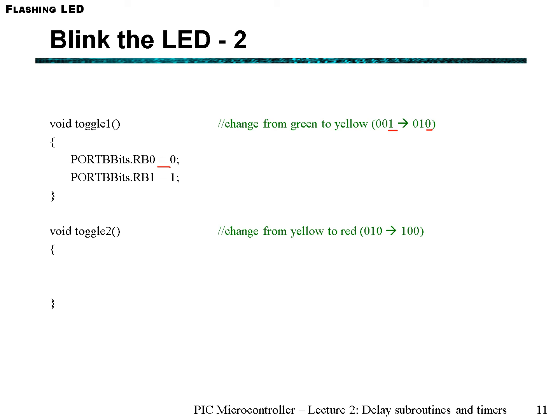So we're clearing bit 1, which is the yellow LED, so we're switching it off, and we are setting bit 2, which is the red LED. And now we have this other function called delay 500 milliseconds. And how do we implement this 500 millisecond delay?